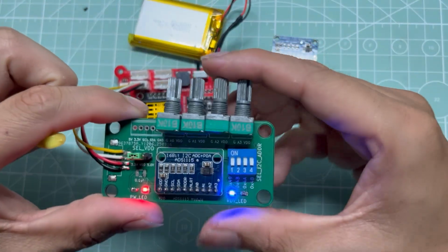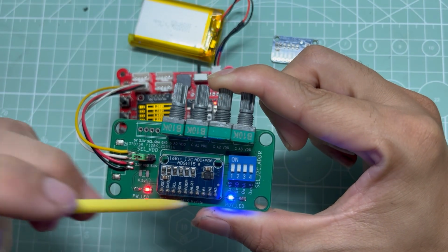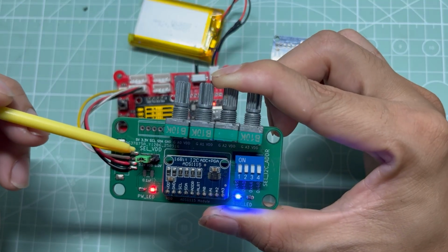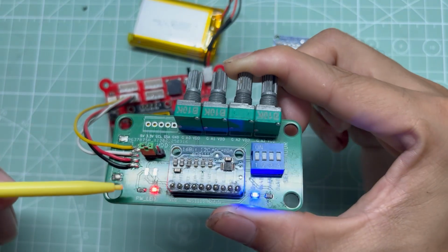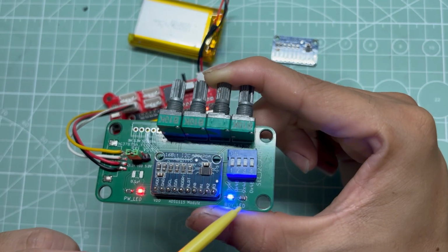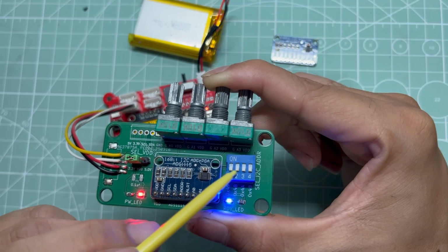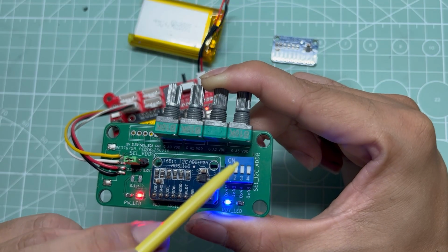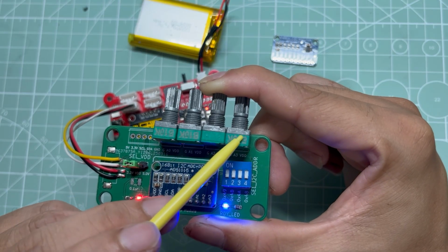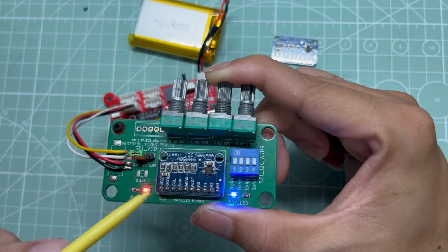To make things a bit more practical, I designed a small PCB for the ADS1115 module some time ago. On this board, I added a jumper that allows you to select a common operating voltage of either 3.3 volt or 5 volt. I also included a dip switch block for selecting the I2C address instead of rewiring the ADDR pin. For this demonstration, I'll be using a standard 10K potentiometer to test the ADC input channels and verify that everything is working correctly.